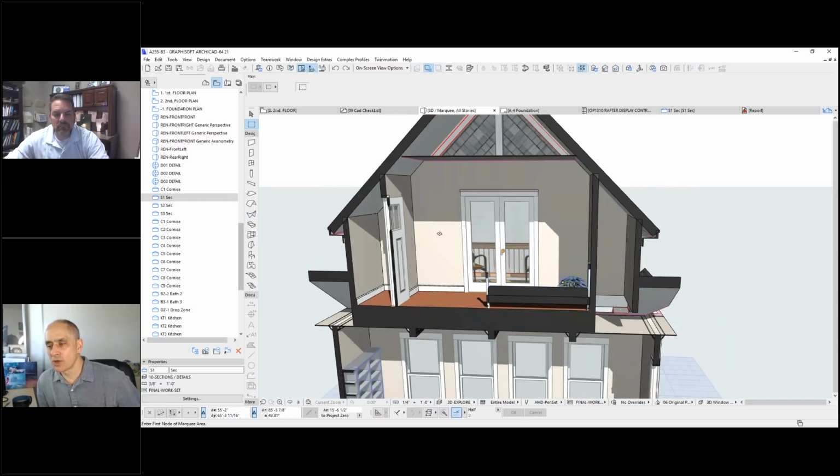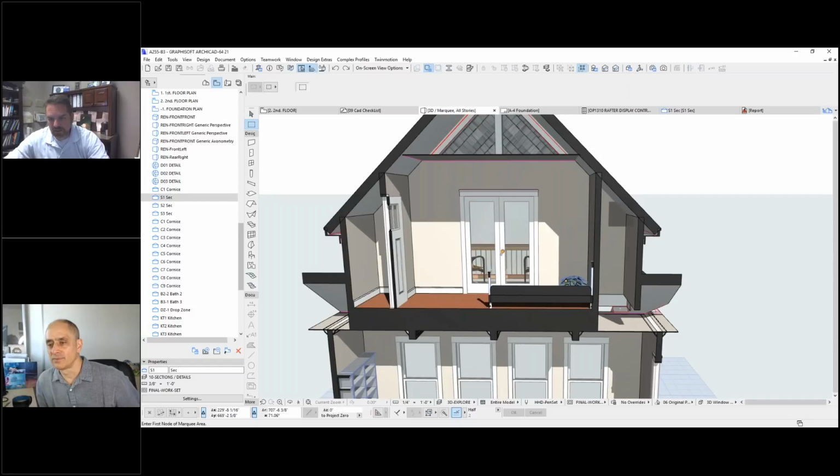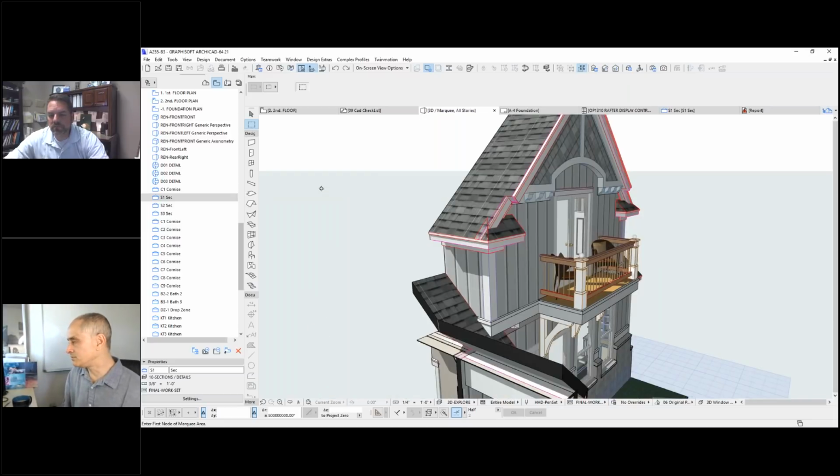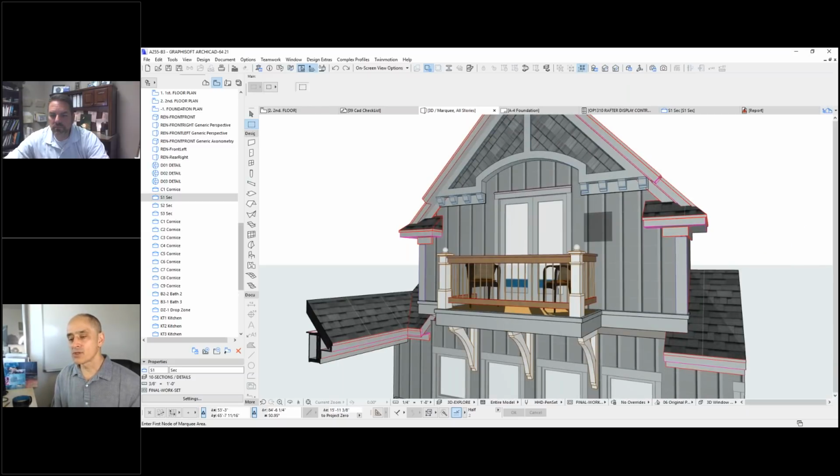So what supported the roof? Did you actually just frame it based on the outside? Yes, I mean it's pitched here, but from our pitch point lines to get our ceiling height, where that ceiling height line was going to be, that's where we placed that pitch line. Okay, so to clarify from a training perspective, the reference line can be placed anywhere you like. Most commonly it's on something related to the wall. It could be the outside face, the outside framing, the inside framing or the inside face. Those are common things.